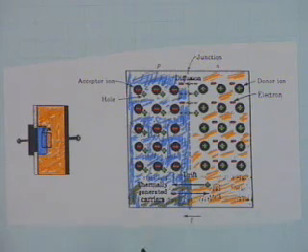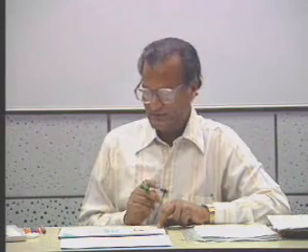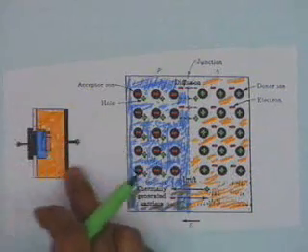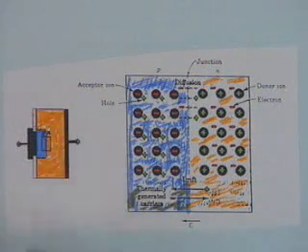All right. So this is why I said in a semiconductor junction, diffusion and drift occupy very important places. If there is to be a current flow through this diode, the current flow shall have two components. One is the diffusion component and the other is the drift component. One must remember that the diffusion component is mainly due to doping, due to the impurity, and drift occurs mainly due to the thermally generated carriers.